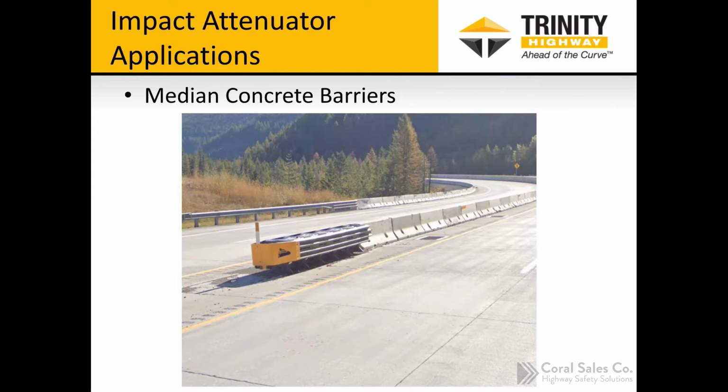There are some subtle differences as well. I wasn't going to get into the exact specifics of those today. I can certainly do that, or if you have specific questions, we could exchange emails later. But for instance, the wide systems do have a hinge to allow the fender panels to flare out where they attach to the diaphragms, whereas the narrow systems, since the fender panels slide directly backwards, just attach directly to the diaphragm. With the wide system, you have a little hinge that allows it to flare out slightly.